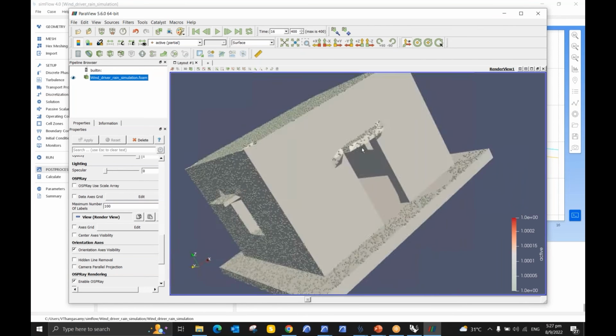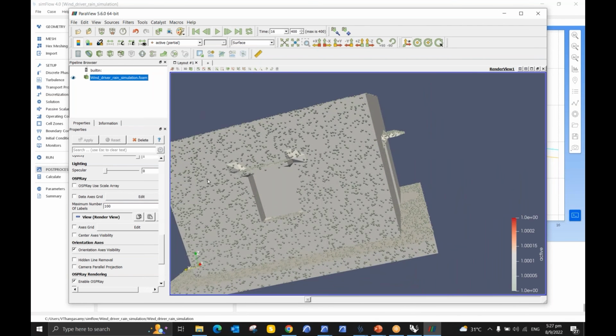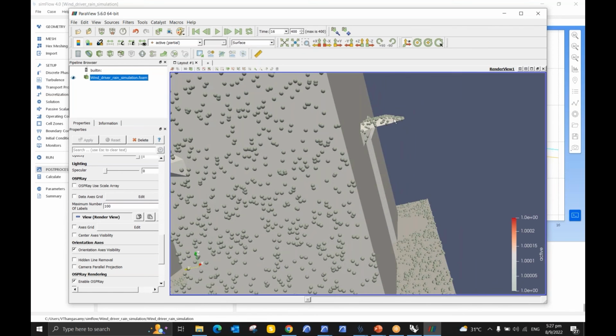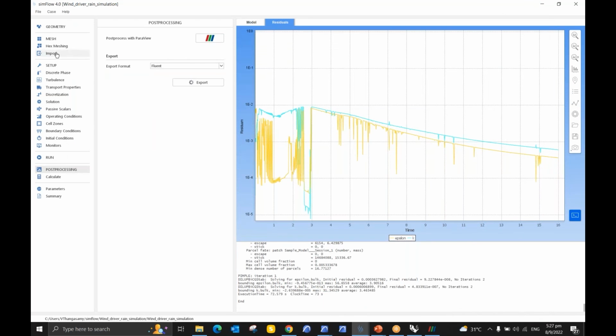And if you see, the building is a little bit distorted because it's not exactly the shape of the building that we have created. Why? Because this is actually not the building, this is the mesh that we have generated based on the building. While we generate the mesh, we need to give a refinement number so that you will create an exact indication of your building as a mesh. Where we need to refine is under the hex mesh. So you select the sample that you have imported, and then you need to refine the number here.